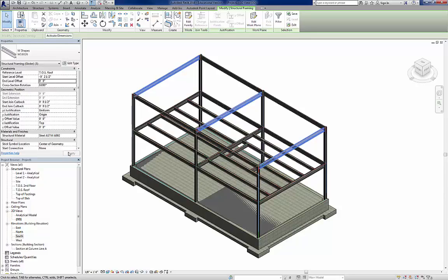You hit apply, you'll see that'll tilt the beams down. And our end level is going to be negative 2.5 inches as well. Okay? The reason we're doing that is we're allowing room for the pan to sit in here on top of them, so that when we pour the deck, it'll be even with the top of the beams.